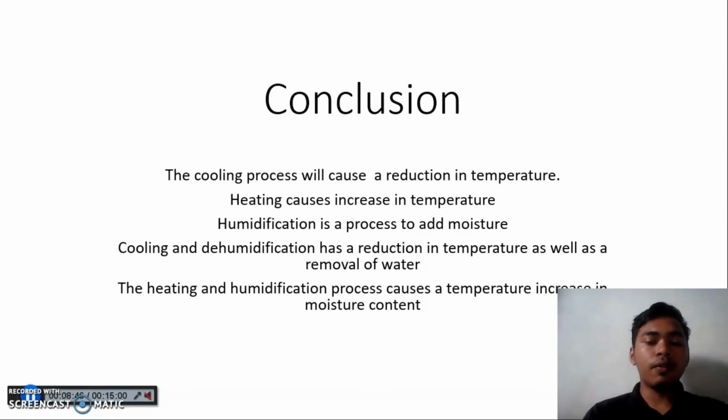For the humidification process, we add the moisture. Other than that, cooling and dehumidification has a reduction in temperature as well as a removal of water, so the moisture content will decrease. Lastly, the heating and humidification process causes the temperature and the moisture content to increase.